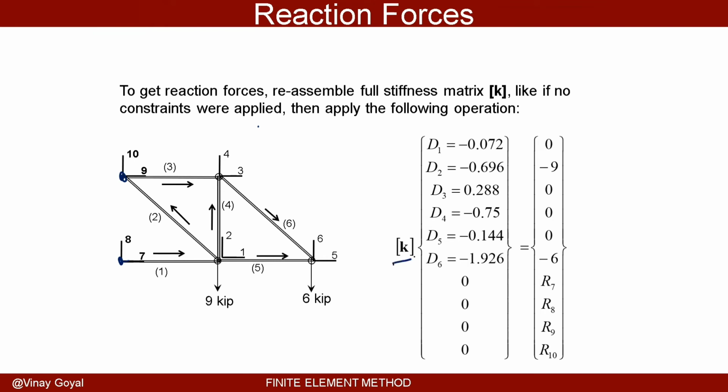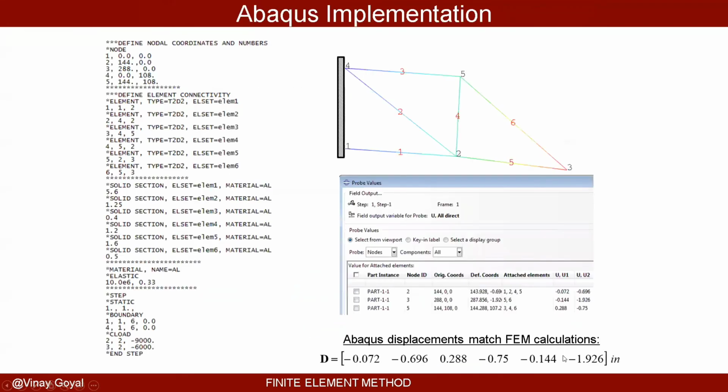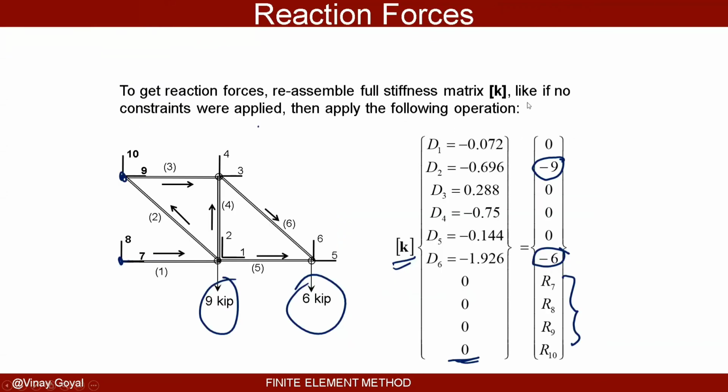So when I multiply that stiffness matrix by this column vector, I will not only recover the forces I applied, which are these ones, but I'll also get the reaction forces. That's beautiful. That's insane and beautiful at the same time. You can check that you get the forces that you applied, but you can also get the reaction forces. Okay.